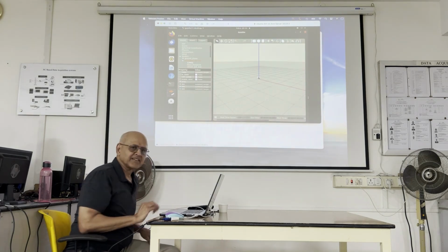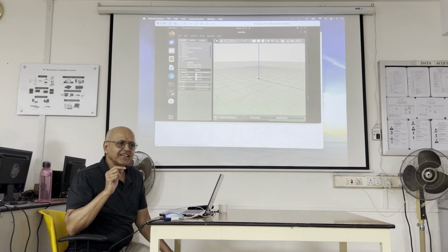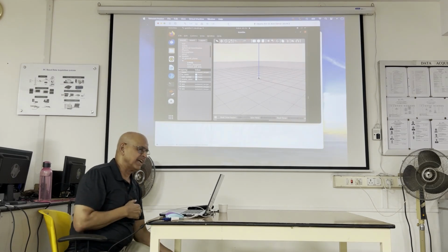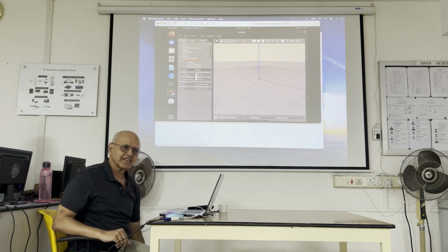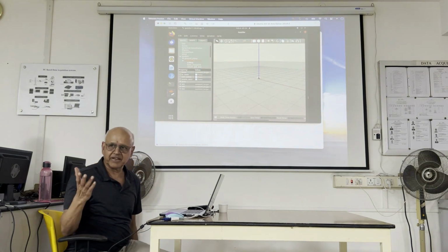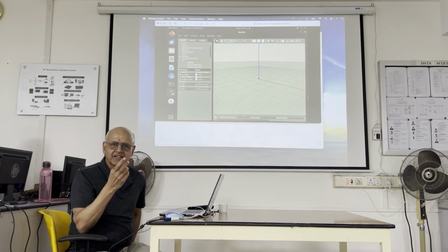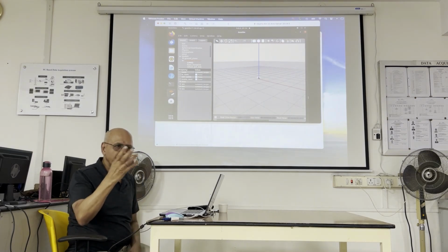This command, in particular the -n1, is designed to echo to the screen. Echo means echo to the monitor, the display. That's what it means. ROS topic echo. So it's saying echo the values of this particular ROS topic. Remember yesterday we talked about topics? That's the way you communicate.